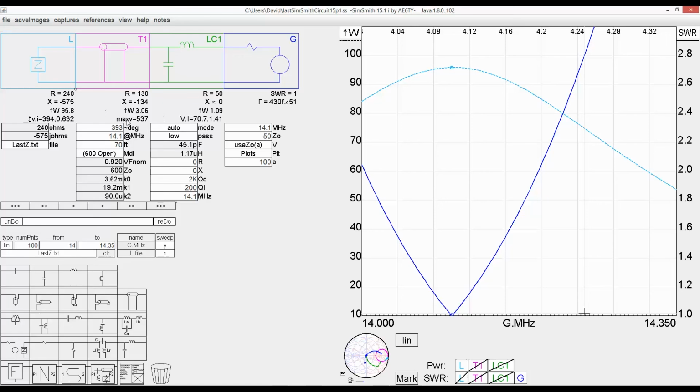Is this enough to make a difference? Well, is this enough to warrant switching from the 450 ohm ladder line to this? It's hard to say. If you're a member of the Last DB Club, then the answer is yes. But you also know that the open wire line is more of a hassle to mess with, and doesn't have the convenience of the ladder line. So under dry conditions, might not really be worth it. Under wet conditions, snowy or icy conditions, it definitely would be a consideration.